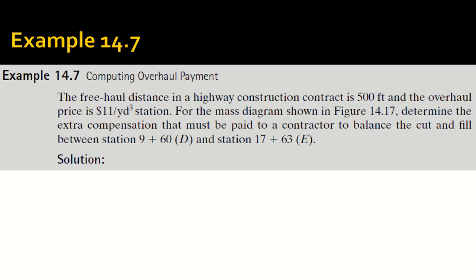But if I have to calculate the total cost, I'll take 11 multiply by what? Stations, right? So he will multiply by stations, and what else? Look at the rate. Okay, so it's 11 per what? Cubic yards as well. So you have to multiply with the stations and you have to multiply with the quantity as well, because he is charging according to two items, right? Per cubic yard material per station.